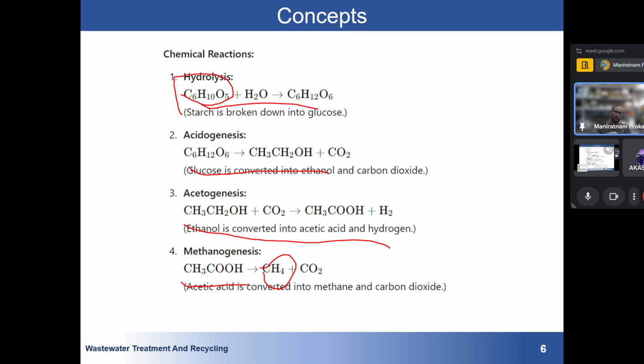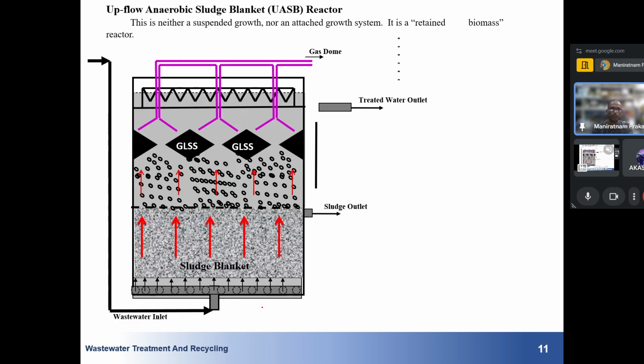So with the help of this, you can write down all the reactions, and you can see how much methane is produced for the reduction of 1 mole of that compound, and based on that you can also calculate the COD. That's why it is said that whatever COD of the degradation has occurred will be equal to the COD of the methane formed. Okay.